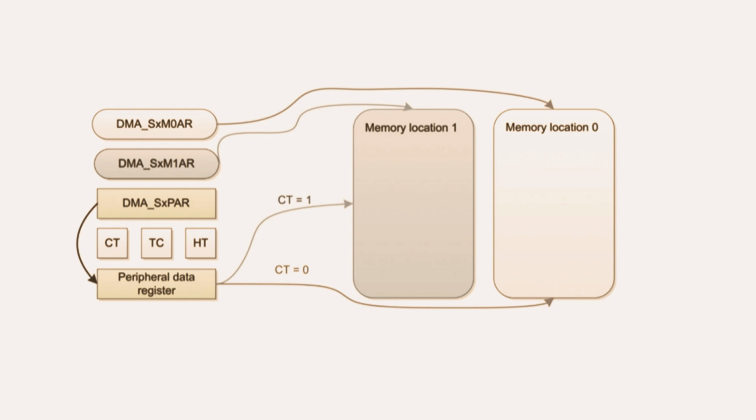Okay, first you decide your oversampling factor, say 16 for that 2-bit gain. So OVERSAMPLE_COUNT is 16. Then in your code, you allocate a buffer in RAM to hold these raw samples, something like uint16_t adc_buffer[OVERSAMPLE_COUNT]. You also need a variable to store the final high-resolution result, maybe volatile uint16_t result_value. Got the storage ready? Then you configure the ADC itself.